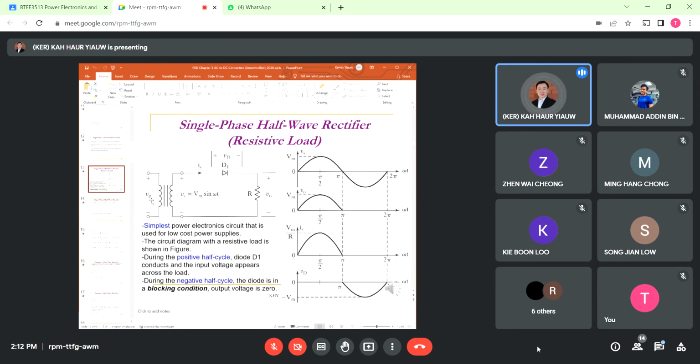That's why I say if the system comes with a transformer, the value at your transformer secondary is in fact the input to your rectifier. So we don't need to care about the primary. We need to work out the VS and IS here in order to do the calculation.